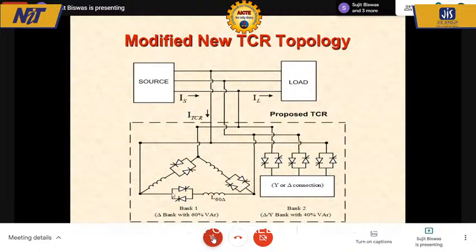The difference is, in this you have phase controlled reactors, in this you have line controlled reactors, and it can be shown with a particular ratio between the two, 60% and 40%. The harmonics created by this will be cancelled by the harmonics created by this, so that the line current is devoid of typical harmonics like fifth and seventh. They get cancelled. So today you can have some of these TCR structures where we have low harmonics.